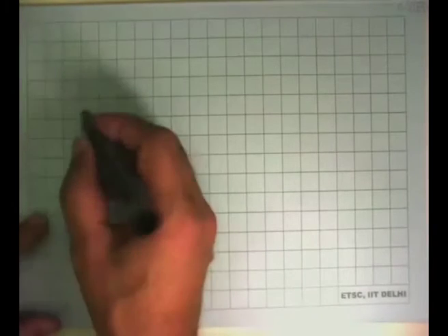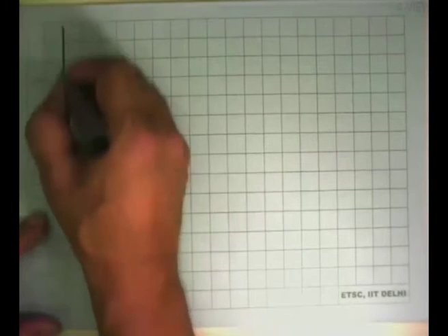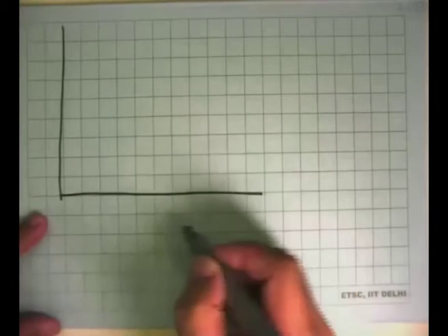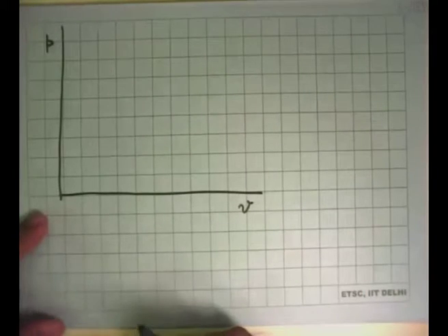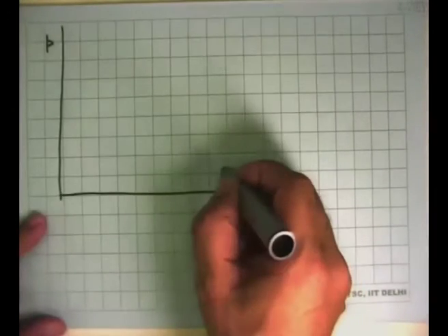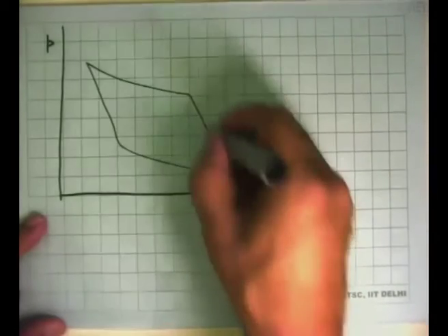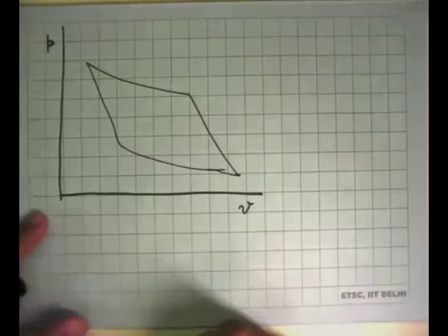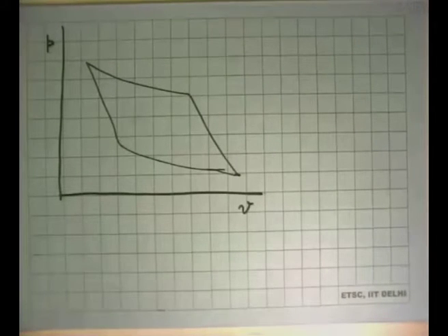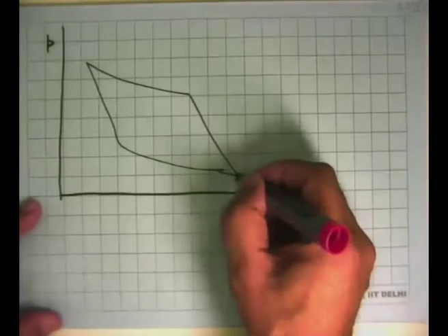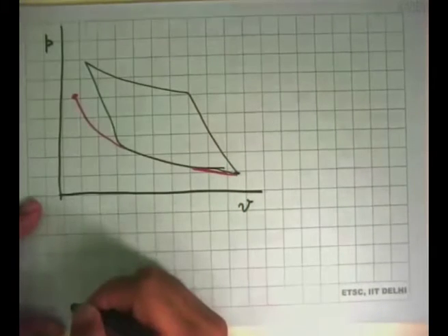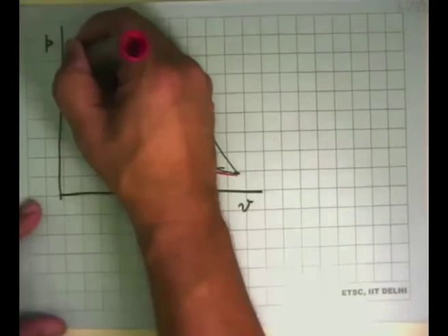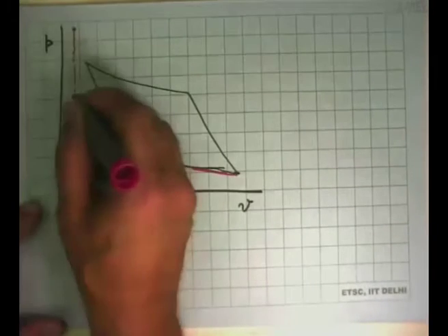What happens in the gas cycle is we modified that diagram and said, look, isothermal heat transfer is not possible. So what we do, and we have to do it on a PV diagram, we saw that PV diagram that was coming up. It was like this, then like this, then like this, and then like that. Not practical. So we said isentropic process I can very closely get, but don't bother too much about anything else. So what we did is we took this isentropic process all the way here. And then we said I can do two things. I can do constant volume heat addition, or I can do constant pressure heat addition.